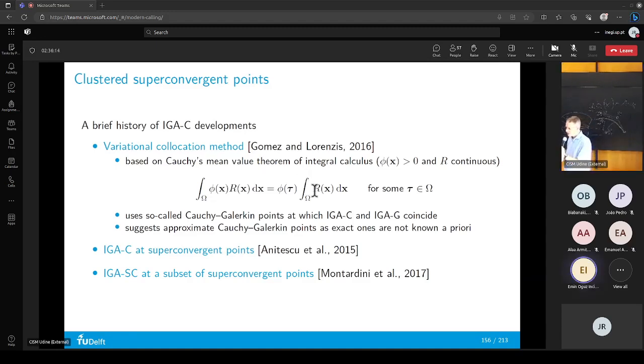Okay, thank you so much. It was clear. Do you call this a Vereshchagin rule? Yeah, a Vereshchagin. Okay, this is known in structural mechanics. It's a way to overcome the integral of a product of functions, where you evaluate one function at a point and integrate the other one. It's called the Vereshchagin rule. Yeah. Okay. Thanks.